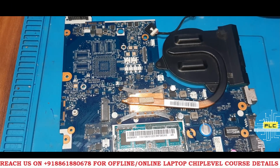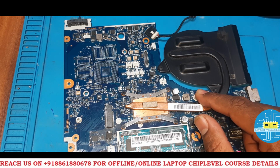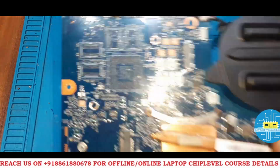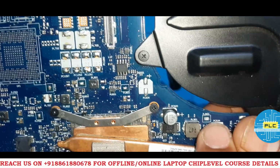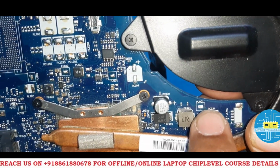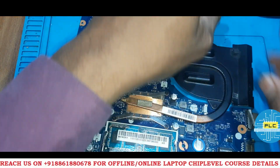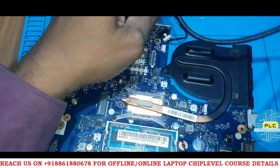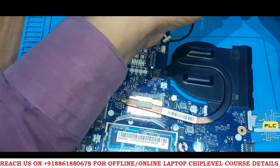See guys, now I have removed PJ901, it's the power supply for 19 volt, 19.5 volts to the particular core section and the graphics sections. Okay, now see once again PJ901, I'm going to show you here. It's clearly removed. Okay, now I'm going to connect this. So what will be the result, that we will check. Definitely I won't connect the monitor, because we won't get any kind of display. So now I am going to connect the power supply and see what will be the result.